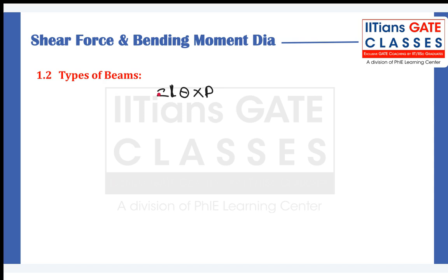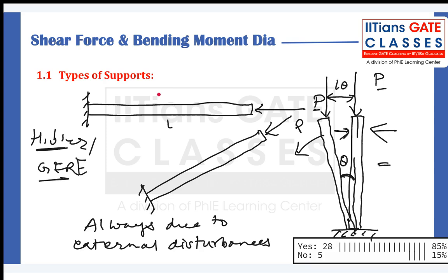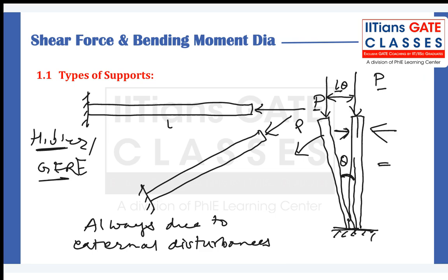Now tell me, this L theta into P about this support acts clockwise or anti-clockwise? It is anti-clockwise, right? So this anti-clockwise moment is a disturbing moment or restoring moment? This is a disturbing moment, right?